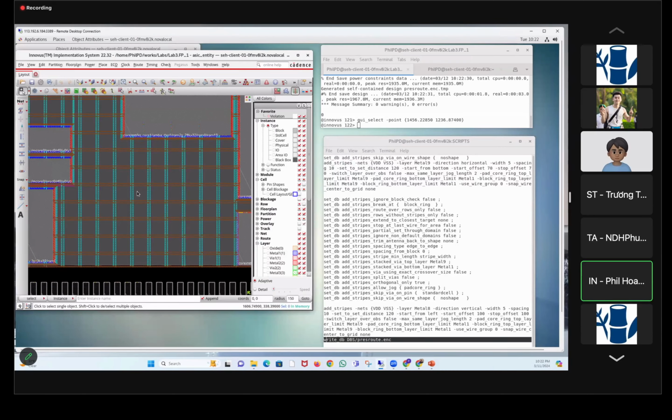On Friday you'll see how this grid is represented in terms of resistance and current taps, and how they are analyzed, and the IR drop to all these different locations, making sure that they meet all the requirements. So that's the grid. These stripes are mainly for the standard cell area. Right, it's a regular grid.